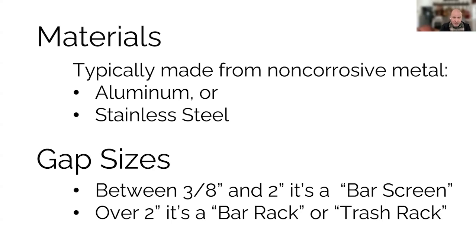And it's really important to clean those because, like anything that you put in a channel, bar screens cause head loss because they restrict the flow. So if you look sideways, and I'll show you a picture here in a second, the flow below the bar screen is typically going to be lower level than the flow above it because of that head loss that the bar screens induce. And the more trash that builds up on it, the more head loss you have, and the more the influent velocity upstream of the bar rack decreases. And you really want to be maintaining specific velocities at different parts of the treatment process for reasons that we will get to in a minute.